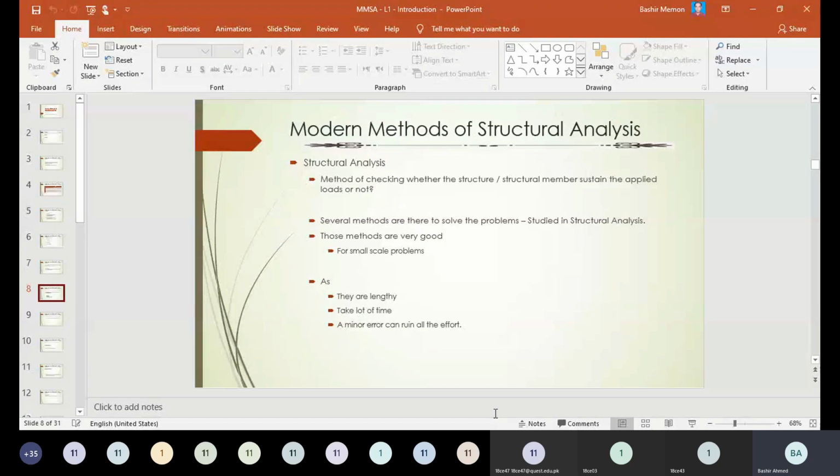The concrete in the vicinity becomes powdered. Steel is rusted. As a result, the volume of steel will reduce. Whatever the diameter of steel was, it will get reduced, resulting in less strength of steel.